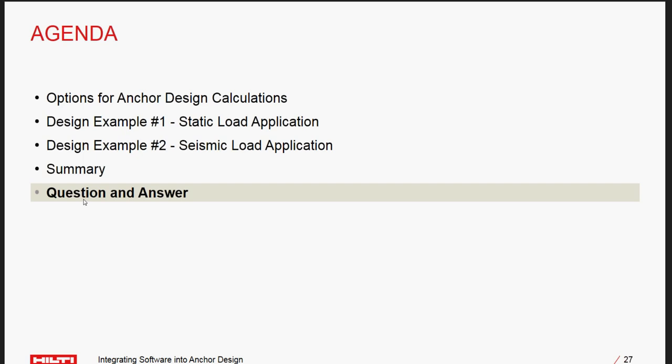So this way you can know that your seismic design is being calculated accordingly. When we're doing a bond strength calculation, for example, certain seismic parameters will appear. I want to point you towards the variables portion, and I'm going to move my mouse to the alpha seismic. That alpha factor, which is very specific to the product that we've selected, has been taken into consideration. So you'll see that, yes, we are taking it into consideration in this check.